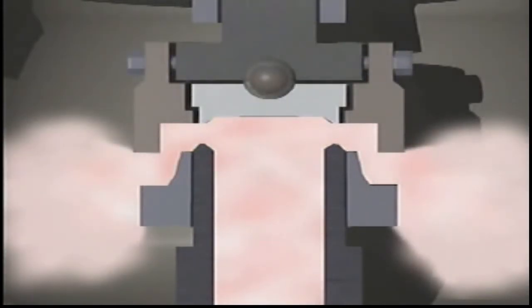While the valve briefly simmers, the flow of the fluid as it discharges outside the valve's seating area increases the lifting force. Then, the reaction hood deflects the discharging fluid downward, creating a reactive force that further increases the lifting force and causes the valve to pop open. As system pressure returns to normal, the valve closes.